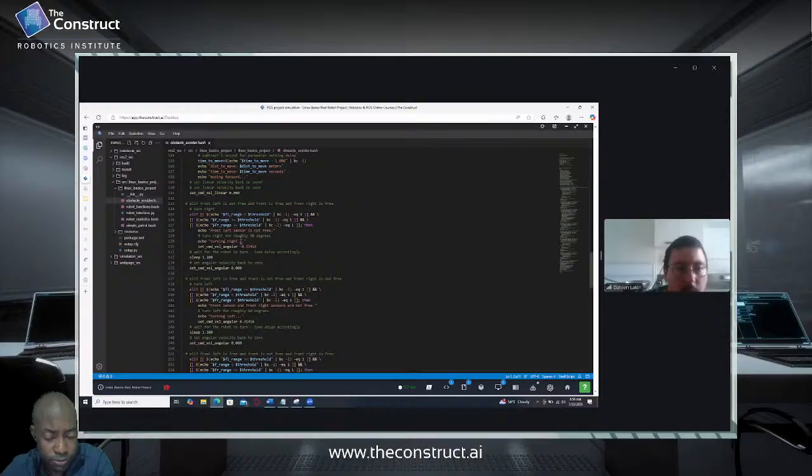This was pretty simple. Just turn right at the defined angular velocity, and again sleep for 1.5 seconds. Perhaps this sleep could be optimized to be a little bit shorter. As we saw, the robot was a little static more than we would like, but this is for safety. And then set back the angular velocity to 0.